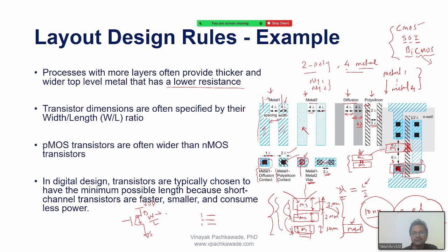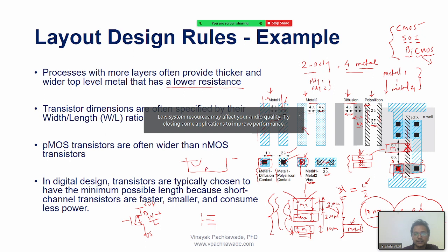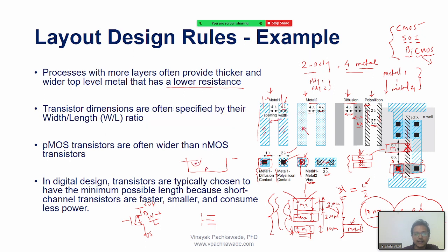And width is, if you see the cross section, like many of you have drawn here, it looks like this. You have the P substrate, then this was N plus region, this was again N plus region, and then you have a small oxide here, and then you have a gate here. And if we look at the three-dimensional view, it looks like that, right?